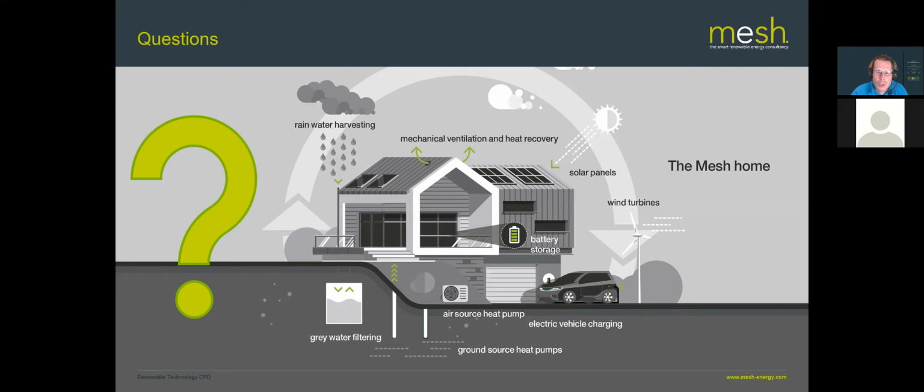So just to pick up on John's question about the ducted air installation, the heat pumps I've been talking about are air to water heat pumps. Air to water heat pumps are eligible for the RHI. Air to air heat pumps do exist, where you're taking heat out of the air and heating air with that heat. That type of heat pump isn't eligible for the RHI, so we usually tend to steer towards air to water heat pumps. But yes, you can do ducted air installations with heat pumps, but you wouldn't get the RHI on them.